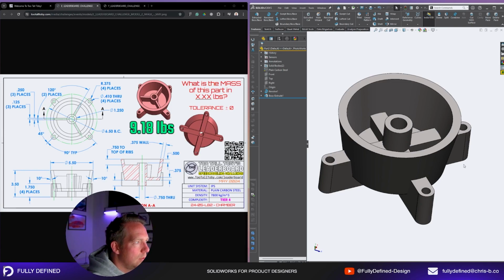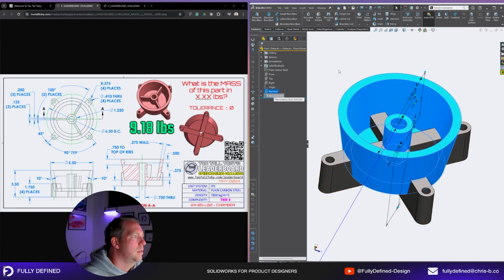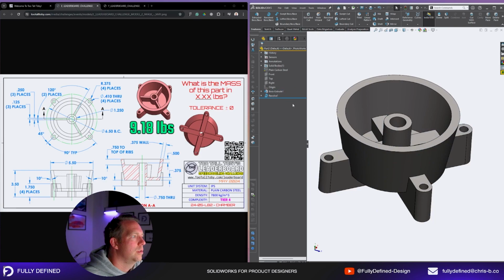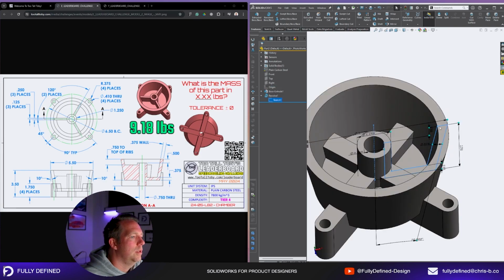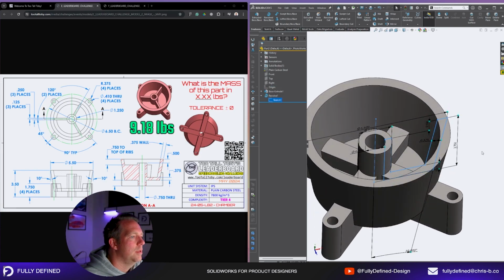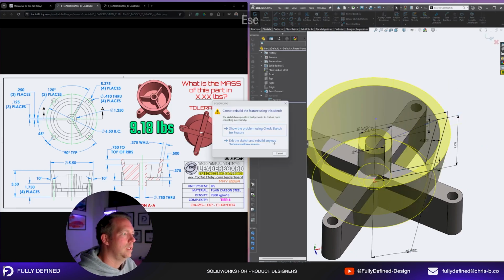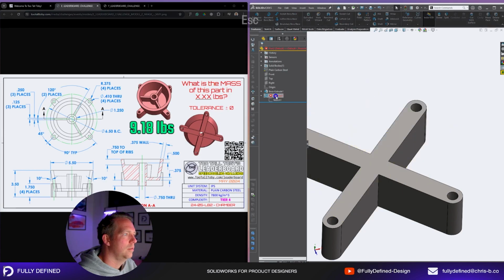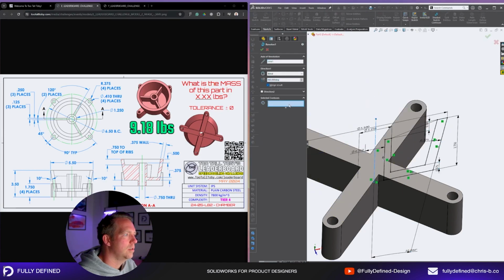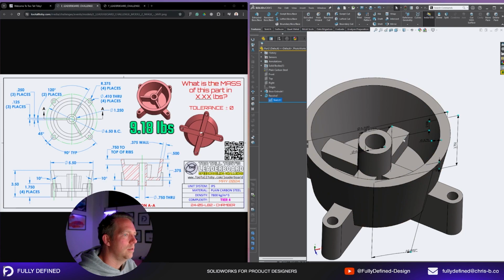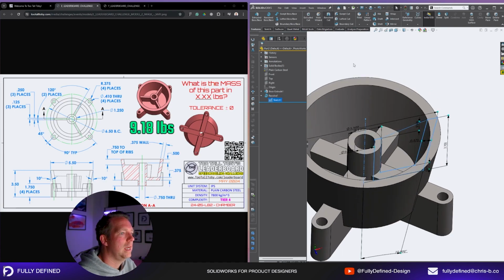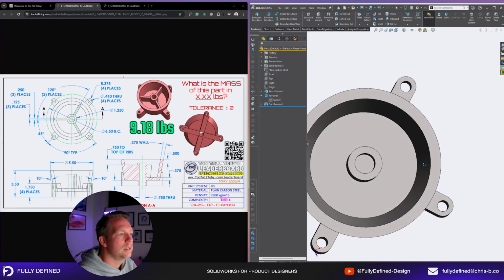It might be doing the bottom extrude first, then doing a revolve followed by a cut, and then the ribs. So it's just going to work here. So we're going to extrude, our revolve, and then we use different faces, different elements of that sketch. So in this revolve sketch, you can just draw another line in here. Now that's going to cause a problem for what we've got first up, but we just need to change the contour selection. All right, and then we can do the same revolve, this time a revolve cut, and we're selecting a different area. See how that worked?